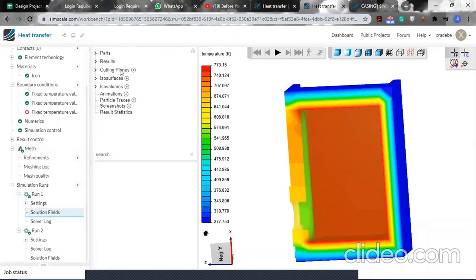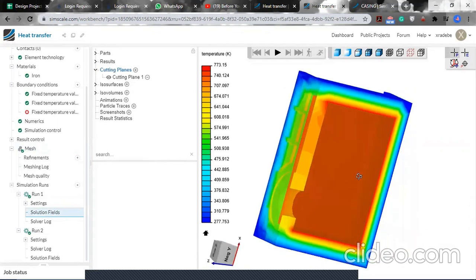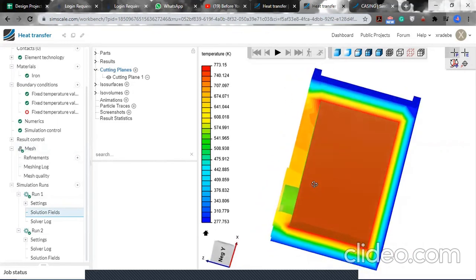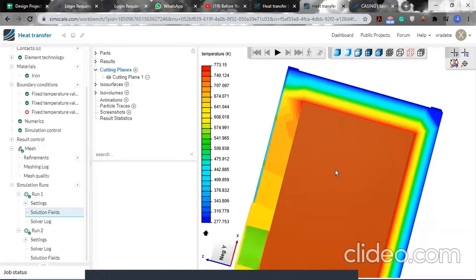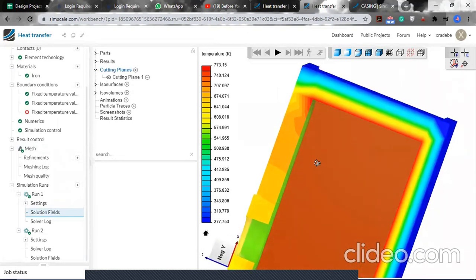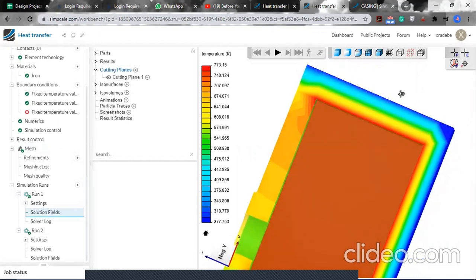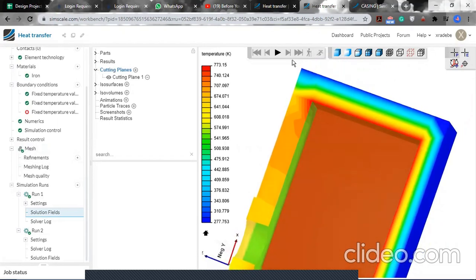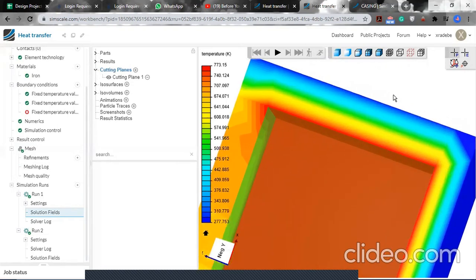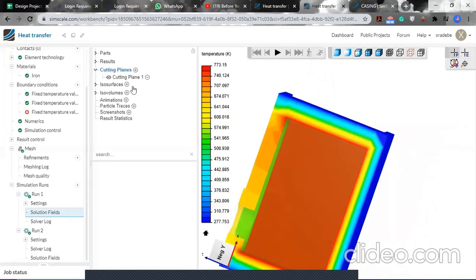After sectioning the results, after cutting the plane on the x-axis, this is how the temperature distribution can be seen, ranging from inside the casing where it's very hot. The assumption is that it goes outside until it reaches the atmospheric temperature. So the temperature distribution can clearly be seen here. It does look a bit linear. It can be assumed to be linear, and then the results are how they came out.